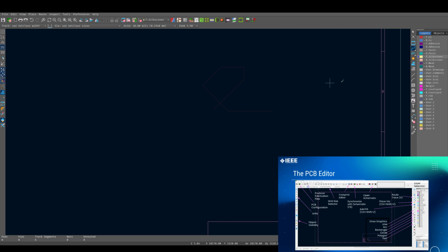So when you're not using a layer, let's see what it looks like. When I'm not clicked on the red layer, it becomes dimmed. That's to make it easy to use other layers without losing focus. This one doesn't really matter, net highlighting. It only matters once you have something inside. It allows you to basically light up everything that's connected to one point. It's good for debugging and stuff.